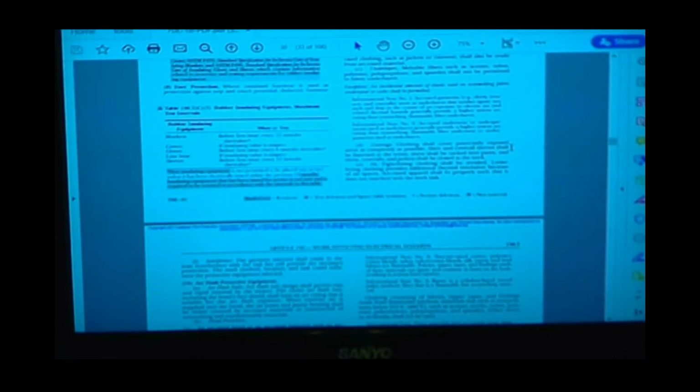What they do is they take the electrical gloves, they fill it with water. They go ahead and drop the glove inside of a tank of water. The water tank right there has got a ground fault detector on the tank. They insert a high potential or a high pot test probe and apply 5 to 10,000 volts to the inside of the glove.